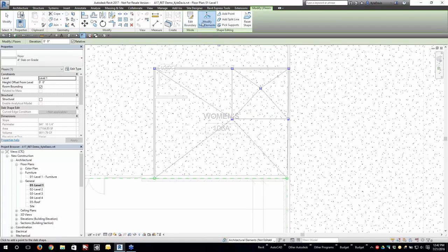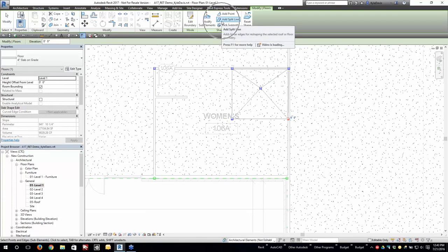Now sometimes Revit will do this, and this is because this point wants to be at a value, so I might have to make sure that these say 0. So I'm tapering the floor at that location only. And again, you might need to add the split lines. If it's not putting it where you want, or you get too close to one area and all of a sudden it breaks that slope, you might need to come back and do that for the slope lines.